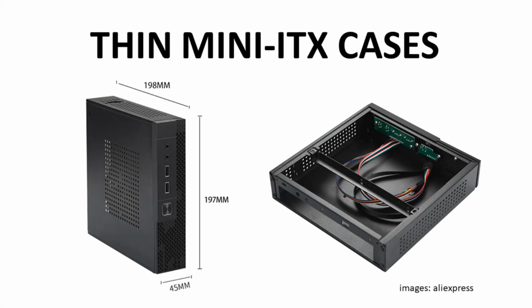How is the thin mini-ITX different? Well, it's not if you use a standard sized I/O shield. If you use the low profile shield, however, you can use extremely small cases. Here is the image of one of these cases. It's only 45 millimeters thick and has just a 25 millimeter tall cutout that will only fit a thin mini-ITX board. These types of cases are often sold as mini PC cases or HTPC, home theater PC cases. To my knowledge, this is the main use for a thin mini-ITX board.